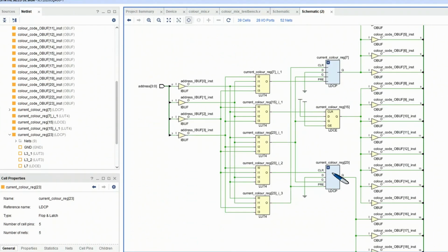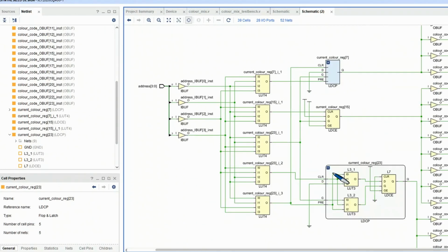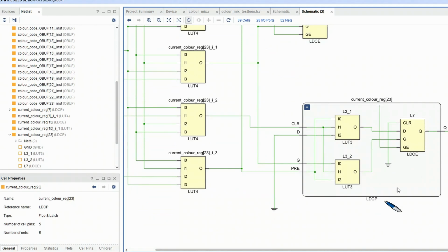Okay, let's look at these ones that we can expand out a little bit. So again, we've got exactly the same flip-flop, but we've just got 2 3-input lookup tables to break down the different possibilities for that. So all of the gates within the FPGA are not actually AND gates, NOR gates, NOT gates.